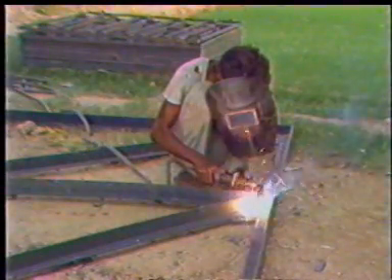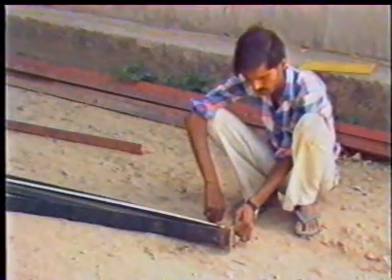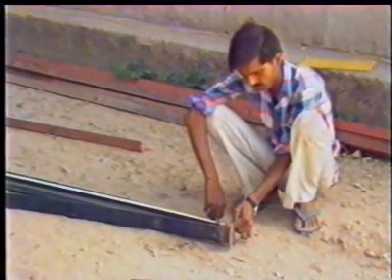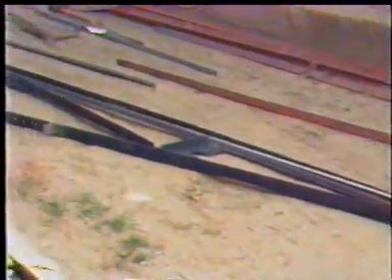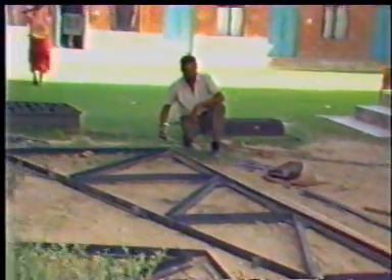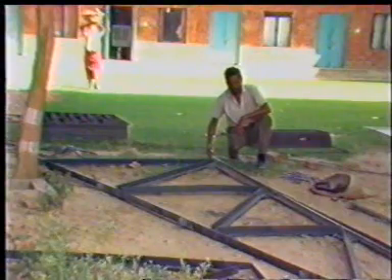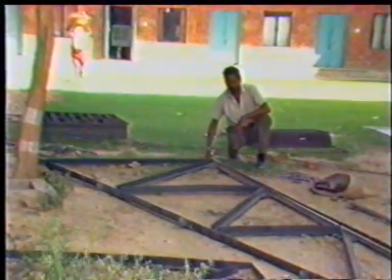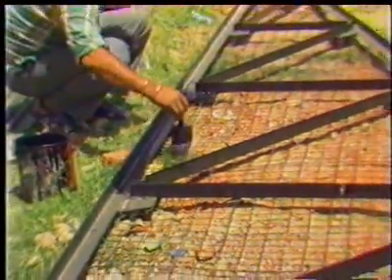Cut angles and gusset plates are then joined by spot welding as per the truss layout. During fabrication, the span and other dimensions of the truss must be checked as per fabrication details. Cleats are welded at predetermined positions on the principal rafter of the truss for fixing purlins. To safeguard against weathering effects, the trusses are painted.